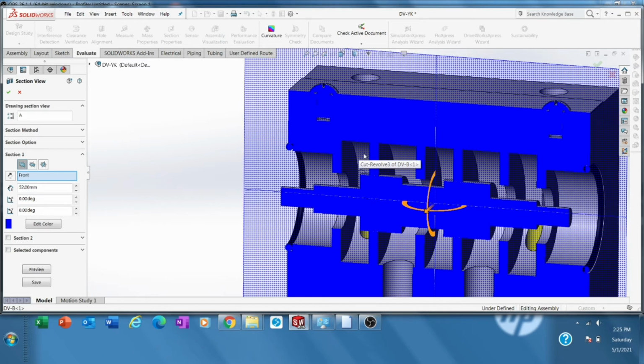Maybe they use sand casting, etc. And it's not possible to use die casting, because the female and male parts for die casting must be openable directly, horizontally and vertically, but this is not possible. In my next video I will also explain that, so you get a feeling about real products. The only possible thing is that they do it by casting, wax casting. You can check on Google how wax casting is done.